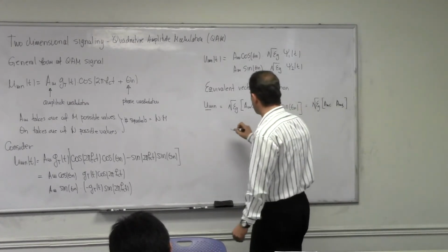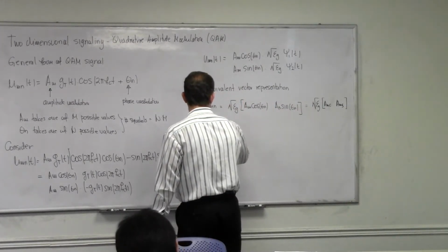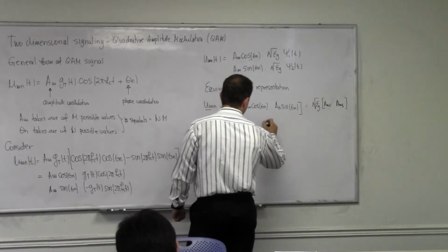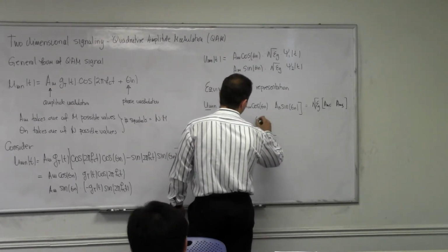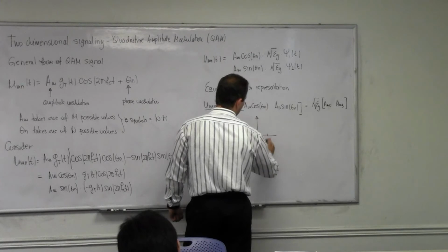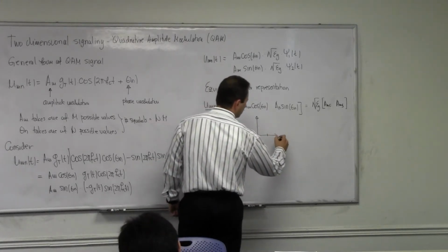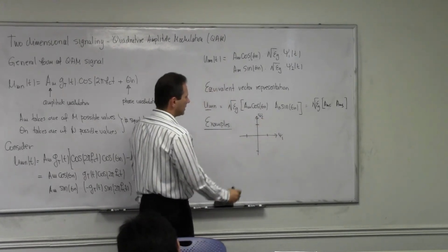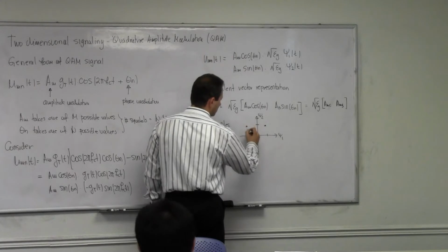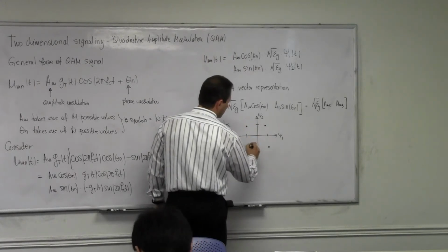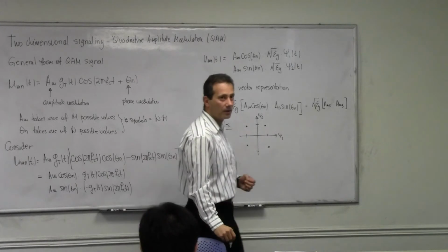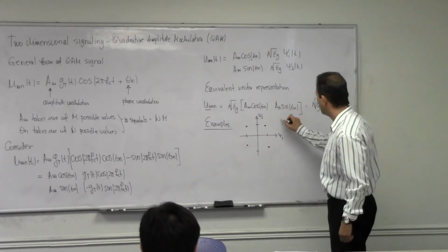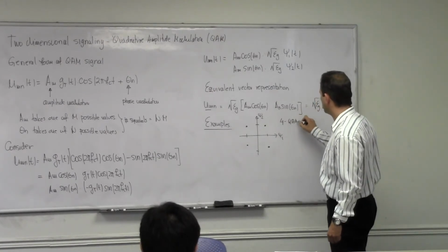Now let's draw some examples. Let's look at the first one, and let's pick two values along this side, psi 1, and this is psi 2. Let's pick two values on this axis, and then pick 4 points, right? So what is this? Well, somebody can say QPSK, and they would be right, but this is also 4-QAM, right?